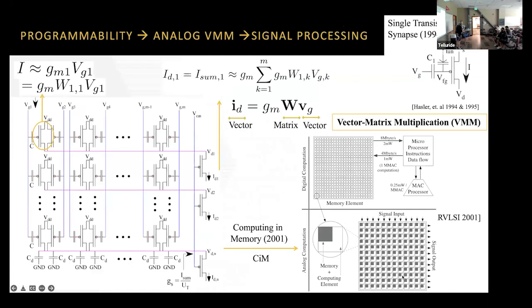So we talked about this, and you can think of it as a vector matrix multiplication, almost tiling in elements here. Basically, we use these like current sources, which allows me to play off the transconductance, voltage in and current out. We did talk about this, but if you need me to slow down, I'll slow down. If I look at the current summation, it is ideal, which is Kirchhoff's current law. Nice when your math is actually a law. And this turns out to give you a sum, which is vector matrix multiplication.